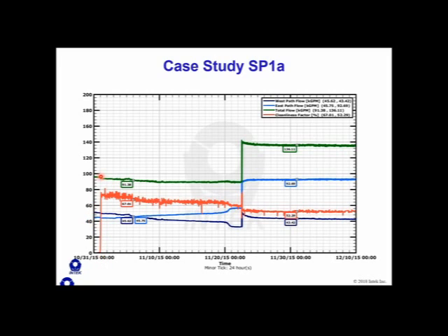So the green line here is the total flow rate through both paths. So the total cooling water flow rate here. The red line is the calculated cleanliness or performance factor for the unit. As I said, this unit has a host of issues. It looks like it came up here with about a 67% cleanliness factor. That's about as good as this unit does with all the issues it does have. So just to give you a baseline for that.